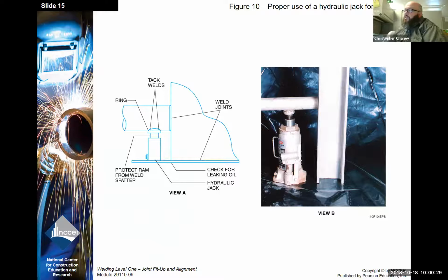This is just using a hydraulic jack for fit up. Hydraulic jacks are quite handy because they are very portable and they're quite powerful, and can be used to align parts or even push parts into place that have started to distort.